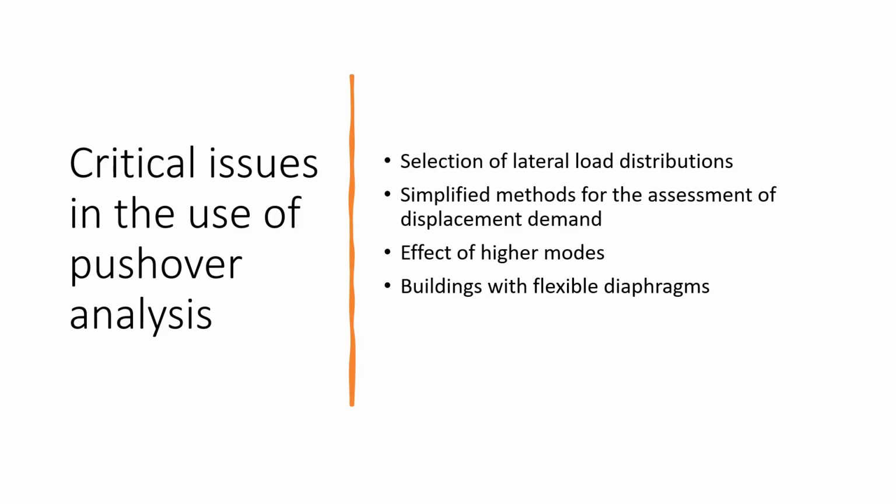The critical issues in the use of pushover analysis can be summarized in these bullet points and in a few slides later on. One is the use of lateral load distributions. We select different lateral load distributions, and using different lateral load distributions, we may obtain different distributions of damage within the structure.